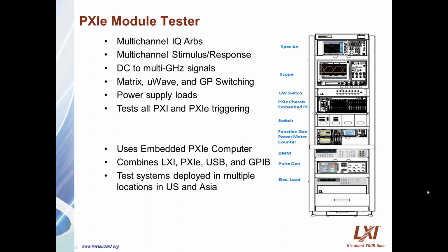language. Each LXI device connects to a multi-port LAN switch, which then connects to one of two LAN ports on the embedded computer. The other LAN port connects to the corporate or company LAN, giving remote access to the test system developers. This configuration was specifically chosen since there are three such systems located in geographically different locations, thousands of kilometers apart, and regular updates to tests and issue resolution can be performed remotely.